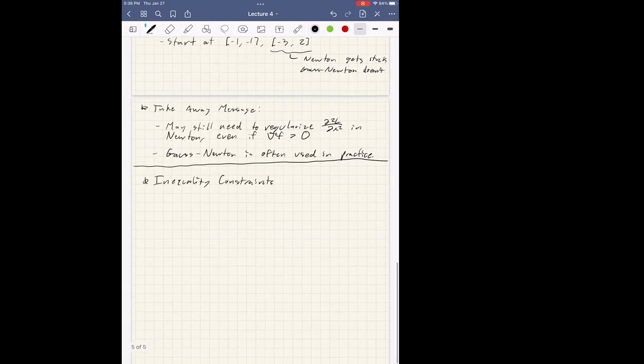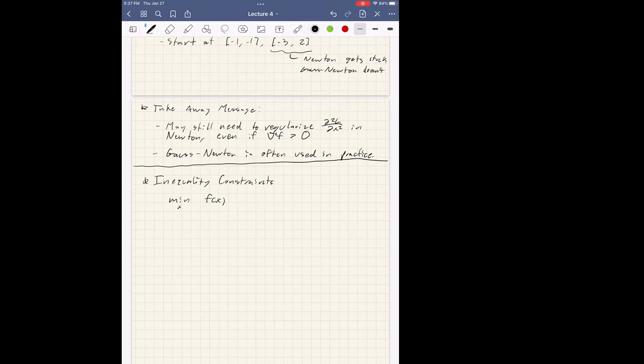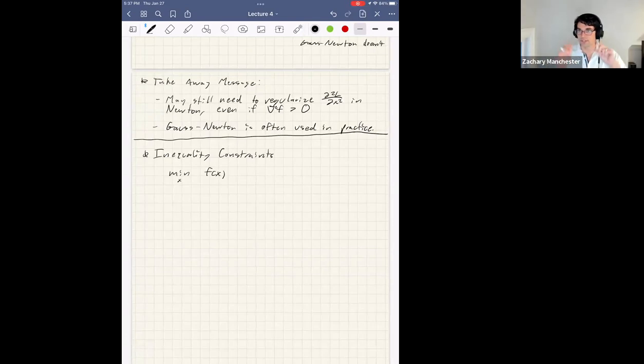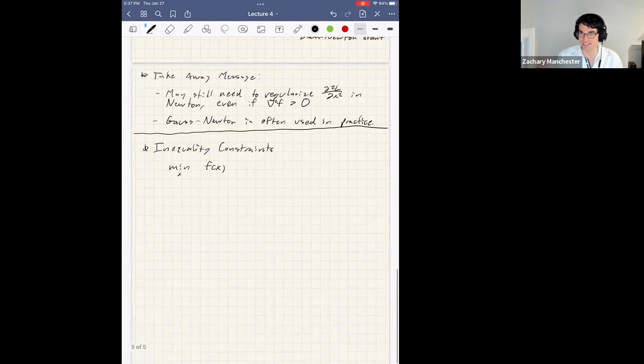Yeah, go ahead. So the equality dynamics constraints, are you basically saying at each time step, the dynamics equal the next iteration? Yeah, if you've got your discretized dynamics, like we talked about a couple of classes ago, x_{k+1} equals f of x_k, u_k, that's your dynamics constraint, right? So your whole x trajectory and your whole u trajectory will be your decision variables in your optimization problem. And you have a whole bunch of equality constraints at each time step saying x_{k+1} has to equal f of x_k, u_k. That makes sense? So do you always need some sort of time horizon in an optimization problem? Generally, yeah. There are so-called infinite horizon problems that you can write down, but you can't really solve those numerically super nicely most of the time. So for finite horizon problems, which is usually what we're going to deal with, that's exactly the setup.